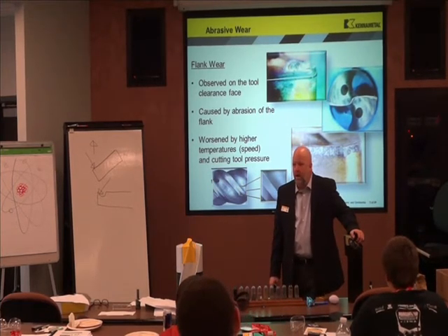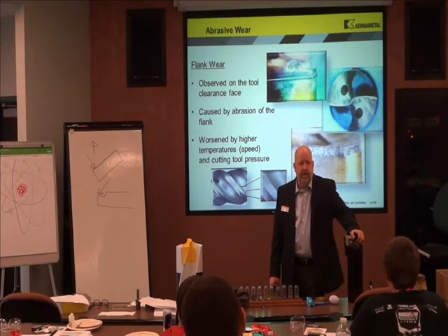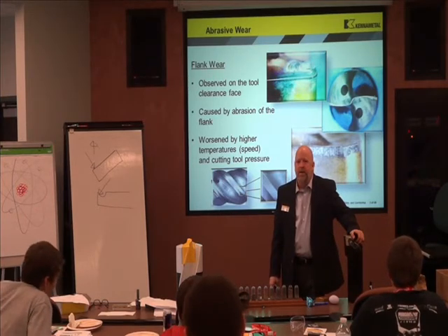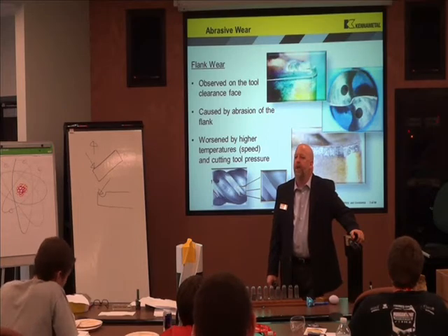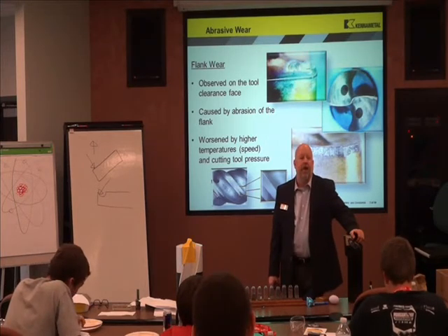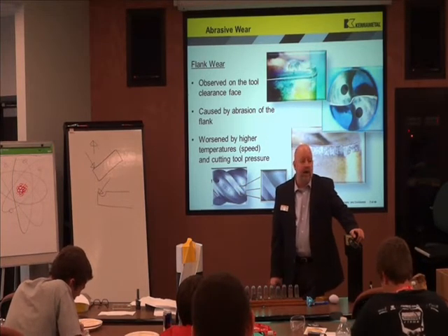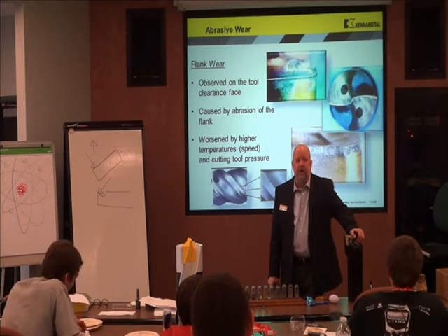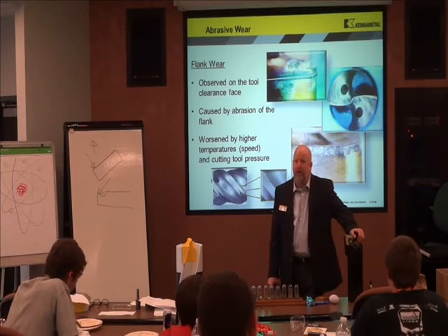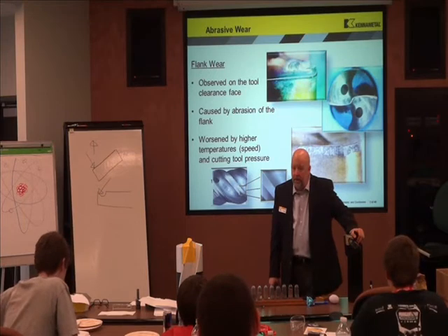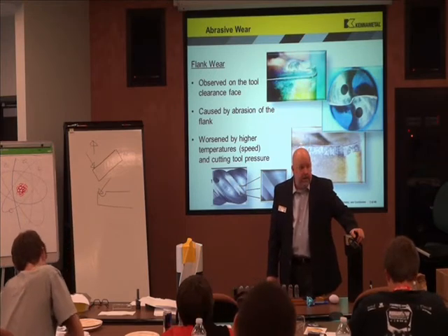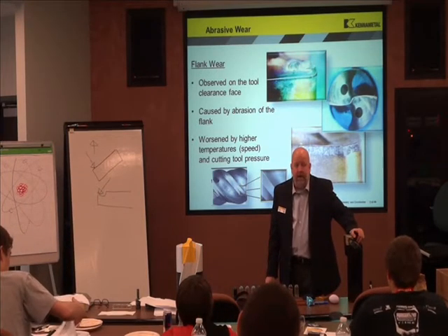On a cutting tool, what color is wear? Doesn't matter what color it is. No. Everybody thinks wear is black. The first thing you need to understand, what is the black stuff on your cutting tool? Carbon. It's the crap in the steel, in the coolant. It's just carbon buildup. It's not wear.